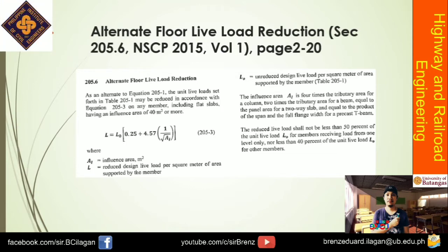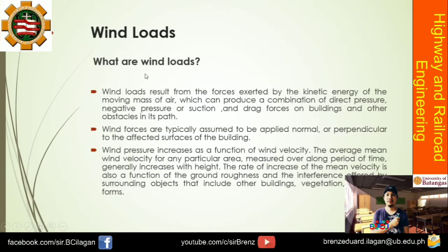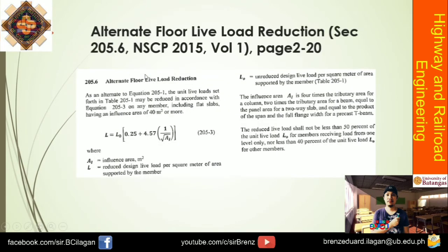Okay, so from that, alternate floor live load reduction. So, under Section 205.6, NSCP 2015 Volume 1, page 2-20. So, the alternate floor live load reduction as an alternate to Equation 205-1. Ba't gumagalaw?